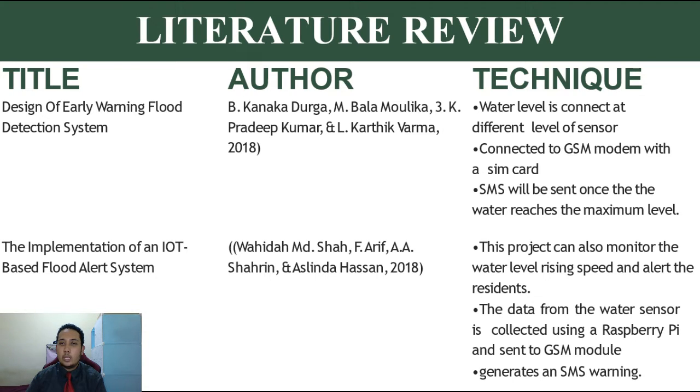Water level sensors will be connected at different levels for this project. They will be connected with a microcontroller. The microcontroller will be connected to a GSM modem with a SIM card. The microcontroller coding will store the mobile number of the user. An SMS will be sent to the registered mobile once the water level reaches its maximum level.